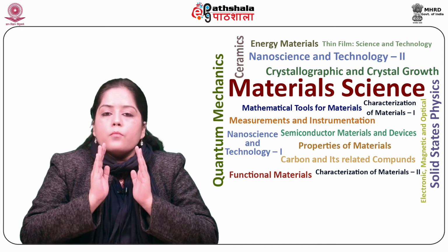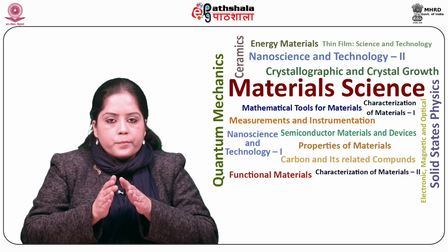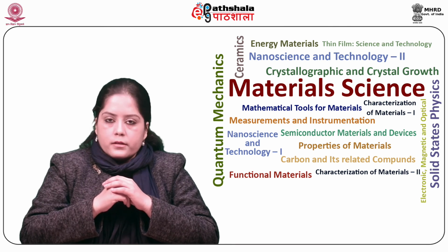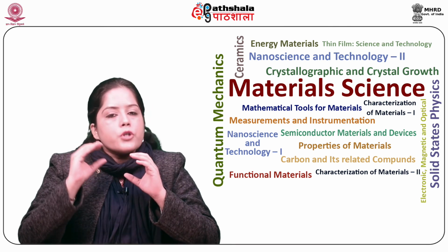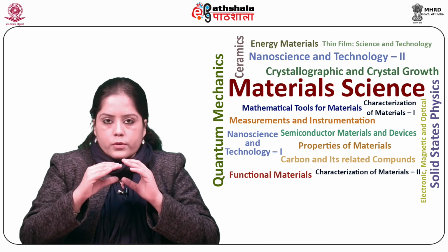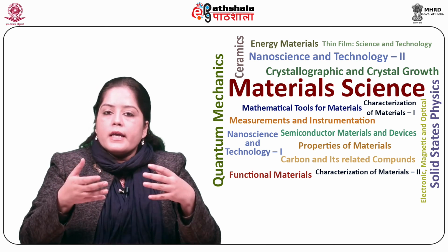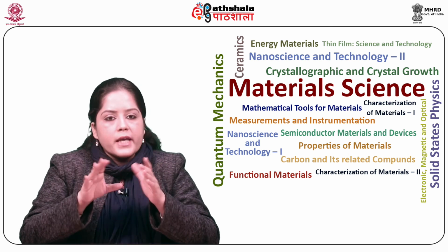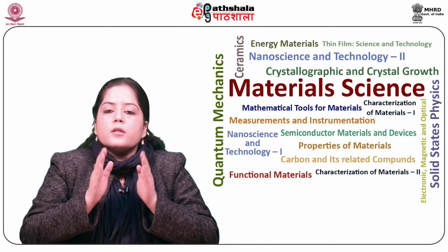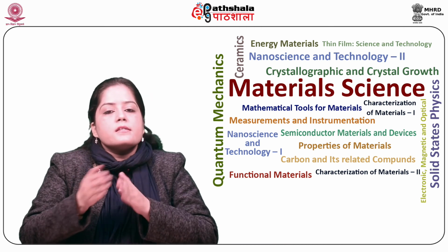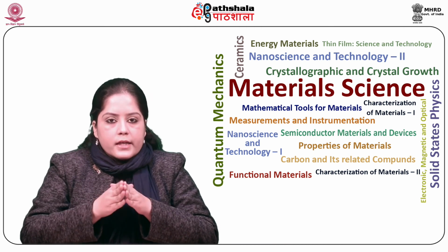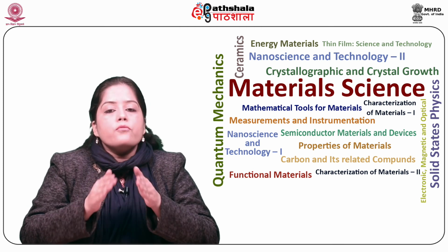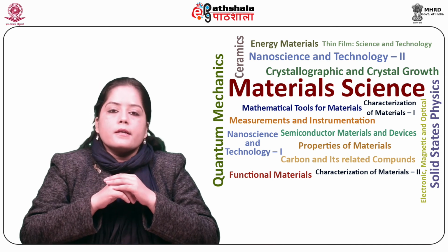So, one of the most popular techniques using this approach is lithographic patterning, where a short wavelength light source is used to create the desired structure. Its main advantage is that the pattern as well as the objects are created at the desired place and no further assembling is required.